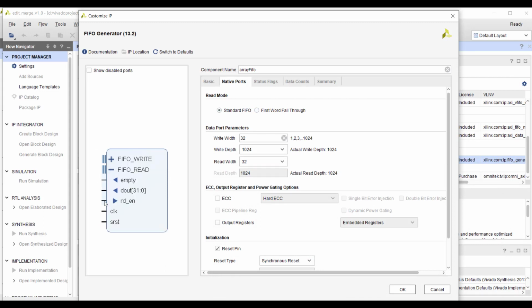So here you have read enable signal high, and again remember there is one clock latency, so you will make read enable high. Only in the next clock the FIFO will see it, it will give the data, and only in the subsequent clock you can take it from the FIFO. Now you can definitely do it using this FIFO, but the implementation will be a little bit tricky.